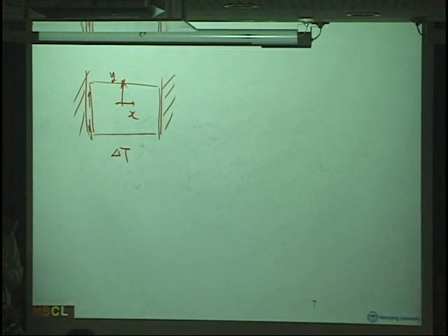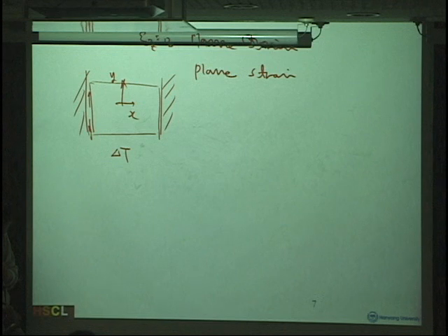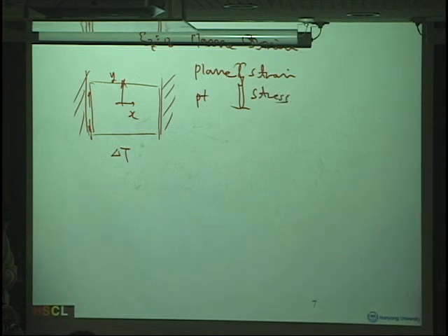And here, rather than a plane stress problem, you can have epsilon z equals 0, which is plane strain. You can have either plane stress or plane strain. In plane strain, you have epsilon z equals 0. In plane stress, you have sigma z equals 0.